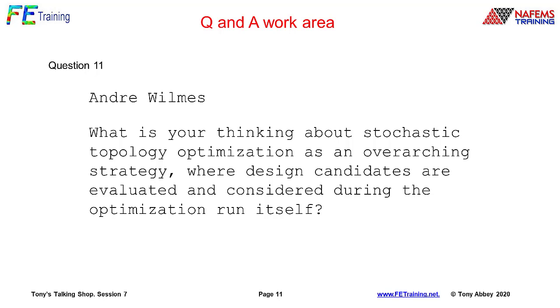I've tended to work mainly with a deterministic type approach, so we've got a particular material property, we've got a load. But I think, particularly with my view, loading is perhaps our most unknown, and perhaps the supports as well. Supports and loading, that's the biggest variation, I think, that we've come across in the real world. So I like to, in a poor man's kind of way, make sure I've got lots of load cases. I cover the load cases.